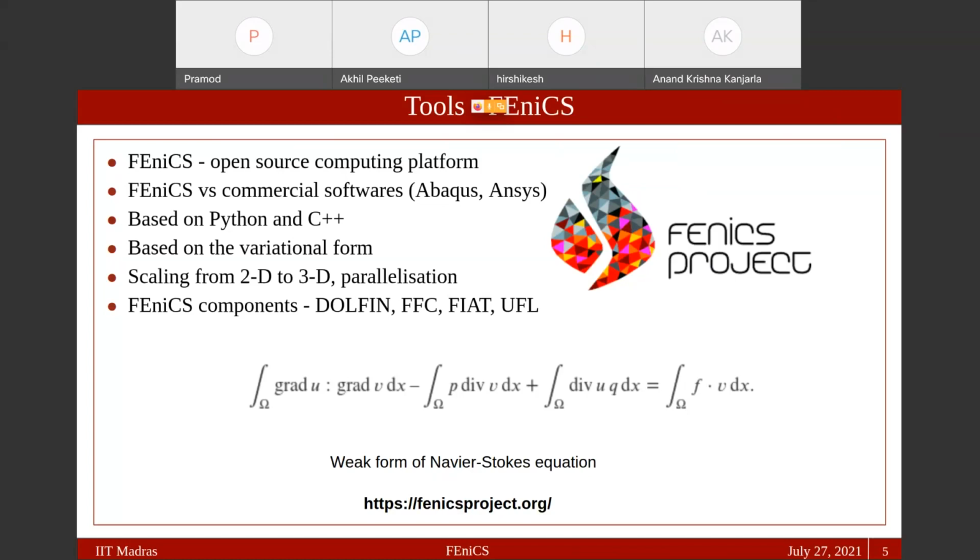Sir, in Abaqus, are moving heat sources included in this workshop? We have a heat source in one example, heat transfer related. Sir, we are working on material science in laser surface modification processes, so moving heat is important for the simulation. What kind of simulation are you doing? Are you doing transient heat transfer where the source is moving, I assume? Suppose we are doing a laser cladding process, where the temperature distributions and the effect of temperature on the stress developed are the main concern.